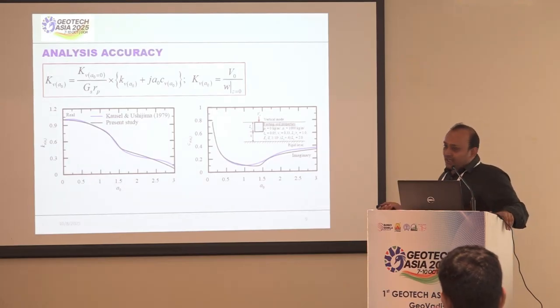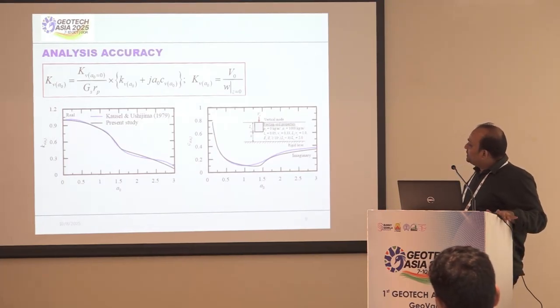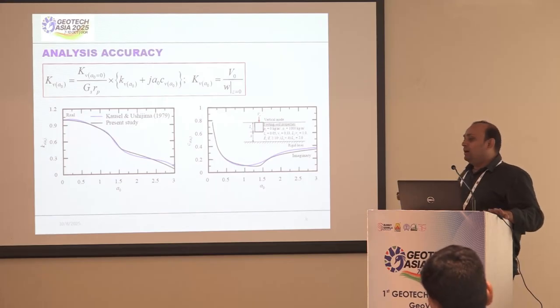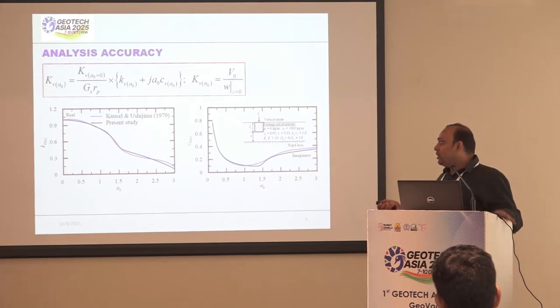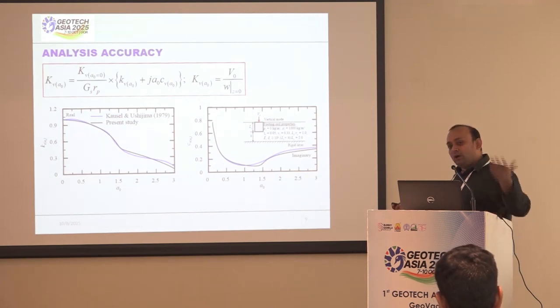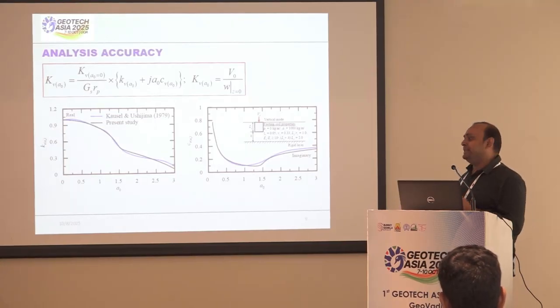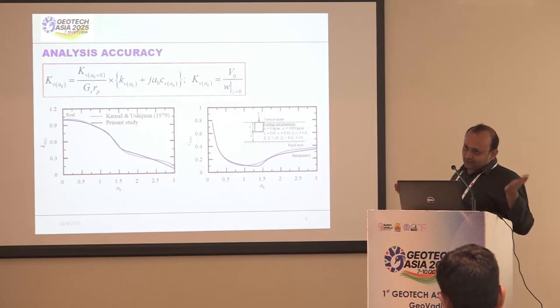So we have validated our model with this particular finite element framework, and we have got a pretty good match for this particular problem. The amount of difference that we got for the static stiffness was about 6.5%. Okay, so we have solved quite a few problems, and there are some differences which could be somewhere around 15%. But it's not necessary that this particular method is completely perfect.